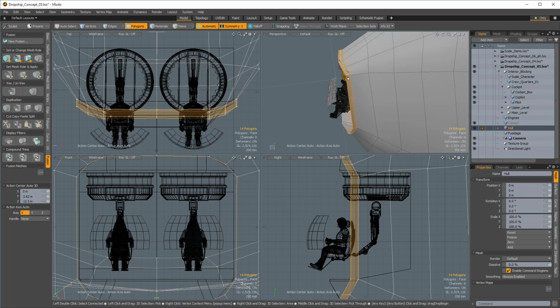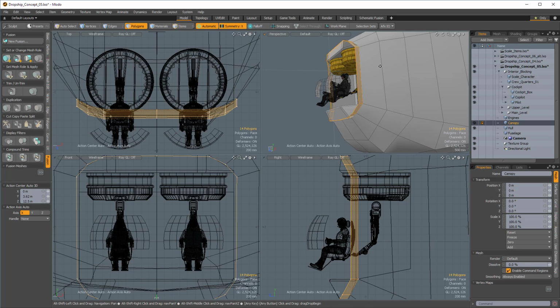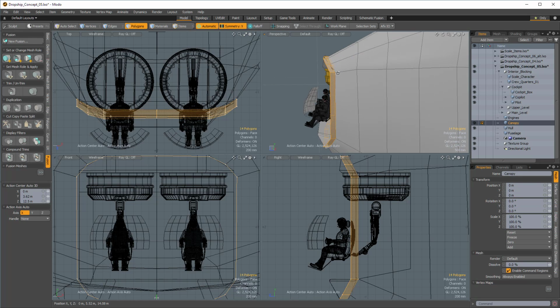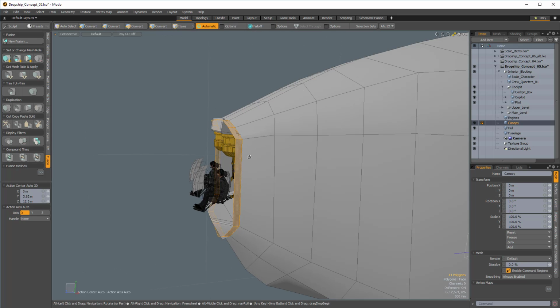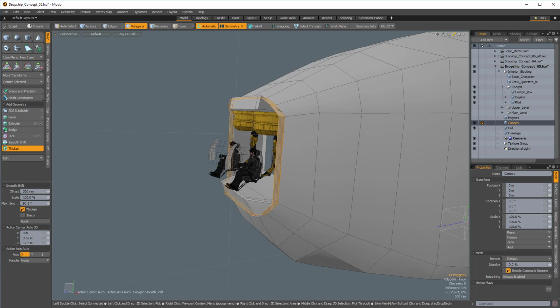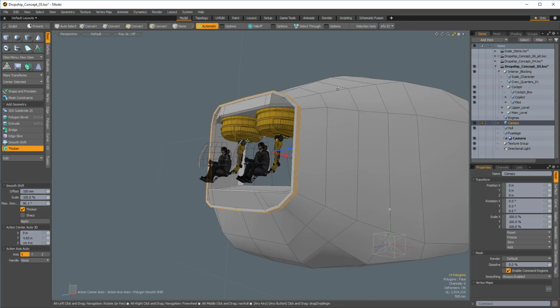And we'll loop select all that, and I'm just going to cut it out because we don't need it in here, and then we'll go up to Canopy and we'll paste that in. All right, and now from here we're going to thicken this both inward and outward, and we're going to do this by doing a thicken and then follow that up with a bevel. So let's go ahead and maximize that 3D view so we can see this a little bit better. And I'm going to go up to the basic tab here, thicken, and we're just going to pull this up about 100 millimeters. Something like that.